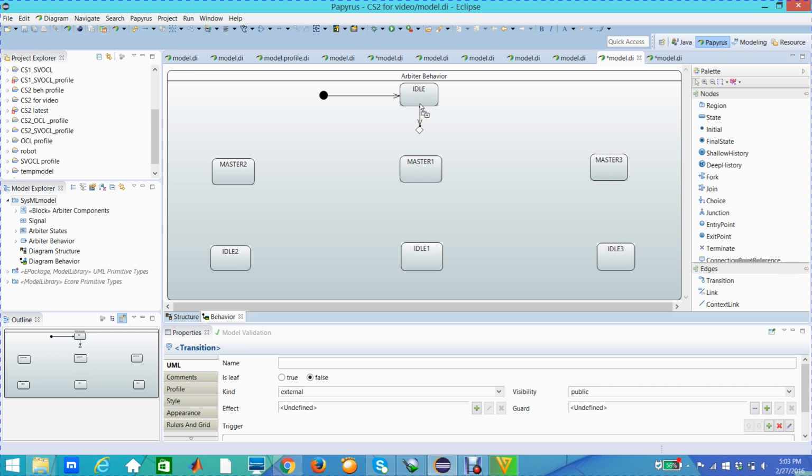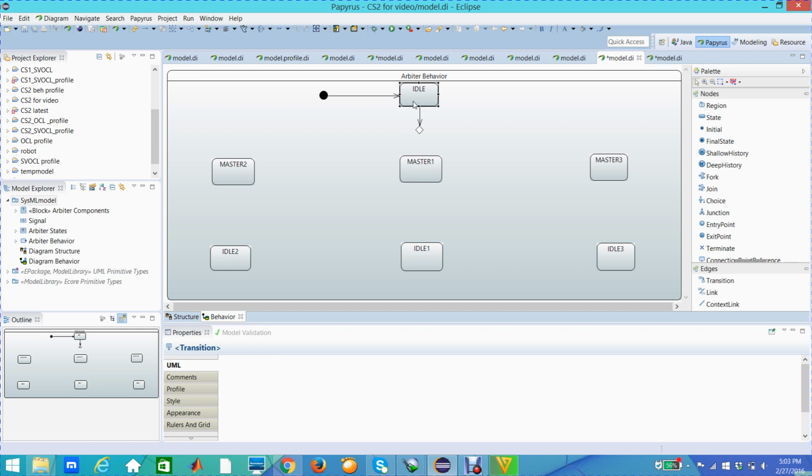Now this transition will be, the system will exit from the idle state upon reset. It is important to note here that in this particular case study, we are dealing with active low signals, which basically means that the reset is active low. When the reset is 0 or false, then the system will get reset and come back to the idle state.